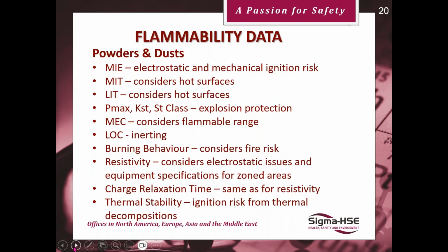Pmax, that's the maximum pressure of an explosion. KST, K is the constant, ST is Staub for dust, so it's a dust constant. ST class, Staub class, used for explosion protection. Minimum explosive concentration considers the flammable range. There's the lower limit, like the LEL.